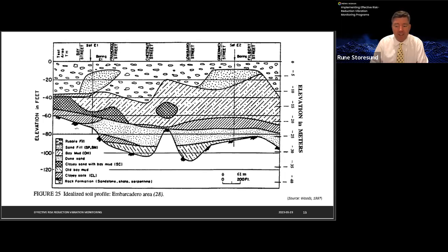However, that subsurface data can be very helpful to those developing the construction-induced ground vibration monitoring program. If you have subsurface data available for your site, which hopefully is all sites, do seek out that information and review it as you configure your monitoring program. Now, I'll assume that many of the participants in the webinar today have geotechnical background or knowledge, so this should be fairly self-explanatory. But if you don't, you should empower yourself to reach out to the geotechnical engineer associated with your project and review the available subsurface conditions to make sure that there aren't any obvious zones of concern.